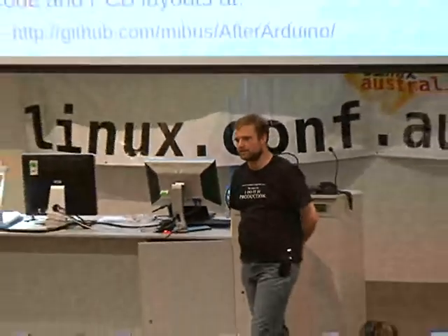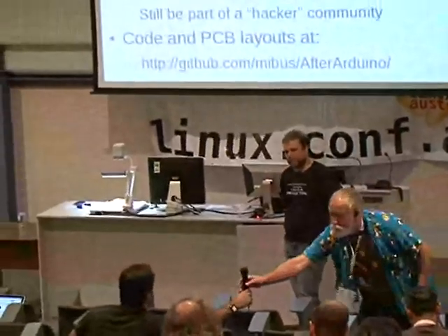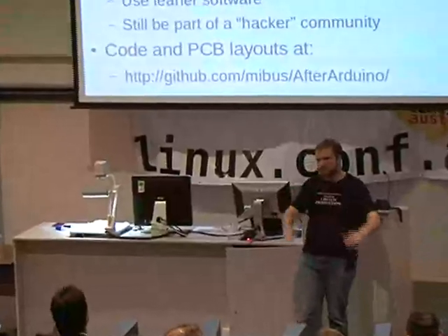And the other thing was the bit shifts. AVR-libc has an _BV macro, which masks away all of that stuff, which makes the code a little bit easier to read, maybe. It does. I did consider putting that in, but I prefer the way it reads this way because it hides a bit less of what it's doing, and it's about the same length anyway.